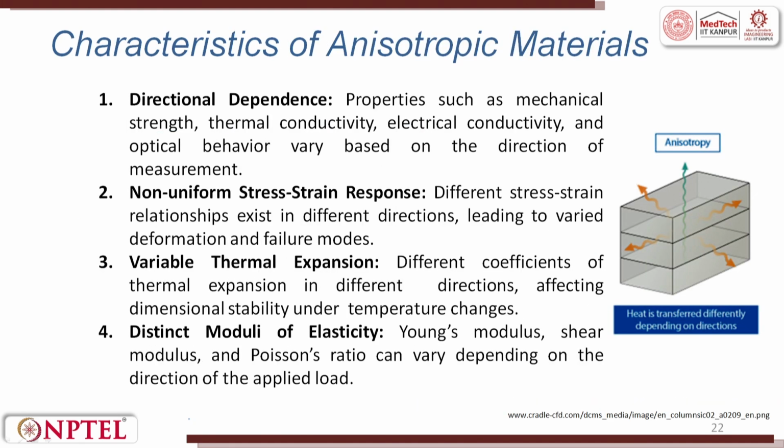What are the characteristics? The properties are directional dependent. What are the properties? Mechanical, thermal, electrical, optical, etc. Non-uniform stress-strain response: different stress-strain relationships exhibit in different directions, leading to varied deformation and failure modes.